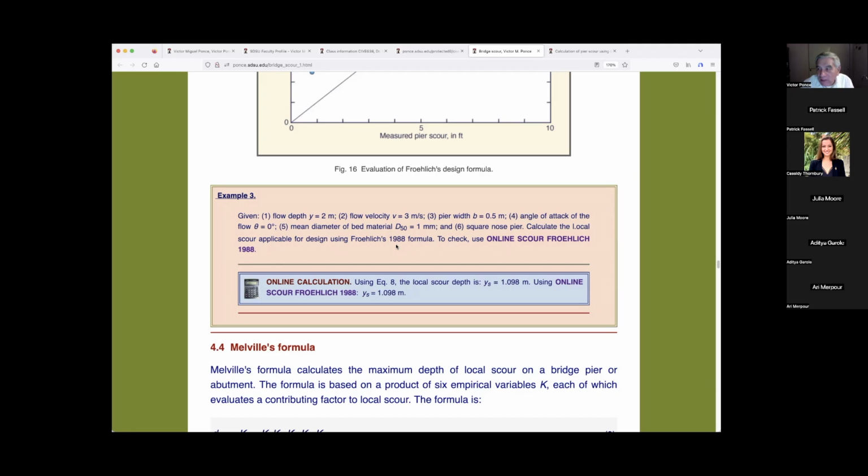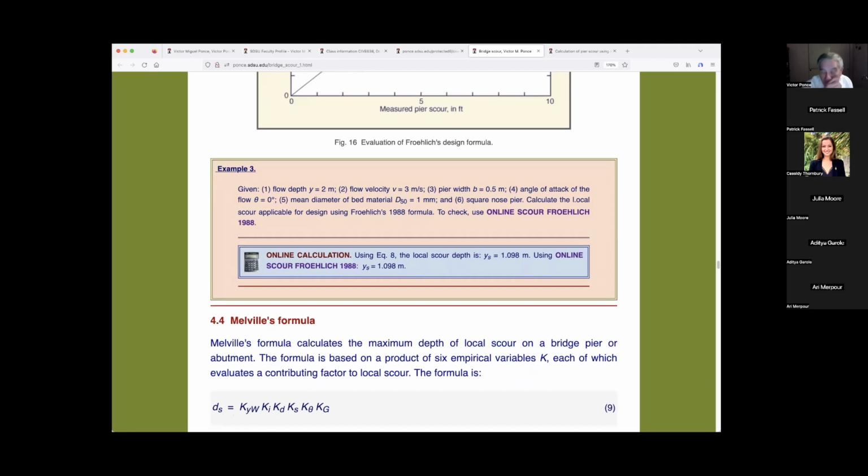And they reduced the factor of safety by half. So if the factor of safety was 9, it got reduced to 4, and by the time 300 people, which were not expected, started dancing on the walkway, the factor of safety of 4 came down to 1, and that was the end of the walkway, right? So it does happen.